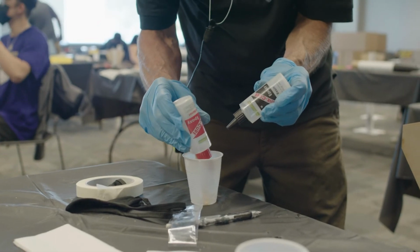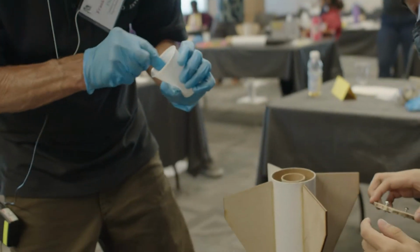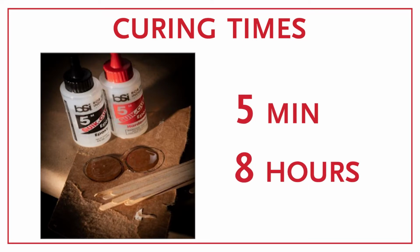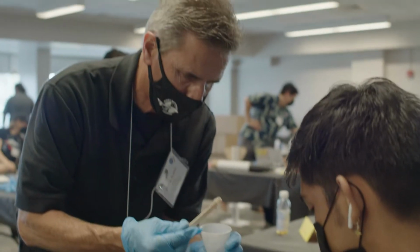Two-part epoxy adhesives consist of an epoxy resin plus a hardener. They form extremely strong bonds with most materials and are favored for a lot of rocketry assembly. They come in many options for curing time, from 5 minutes to 8 hours. However, they have to be measured properly and mixed together, so it is important to not mix too much at a time and to use a timer if curing time is limited.